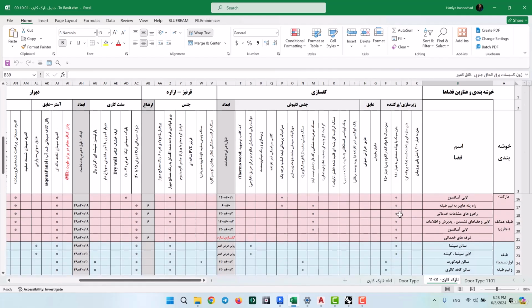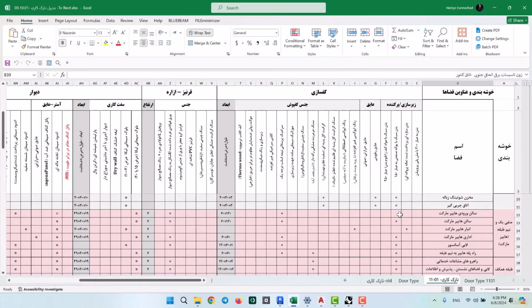So you're just going to have to create the different types of walls and floors based on this table, and then draw them into the project. It's not very complicated, but as for the height of the finished walls, you need to always remember that they need to start from the FFL, or the finished floor level, and then they go all the way up to the ceiling, or false ceiling if there is any.